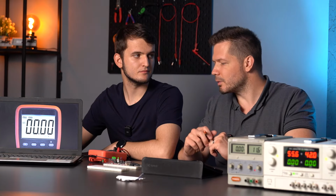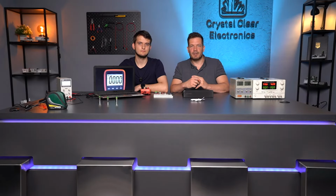One of the most important characteristics of the diode is the forward voltage. The diode conducts only if we connect the voltage high enough to it in the forward direction. We call this minimal voltage the forward voltage. Connecting voltage to the diode which is smaller than the forward voltage, current doesn't flow. In every diode's datasheet, we can find the value of this forward voltage. In the case of silicon diodes, this value is around 0.7 volts.